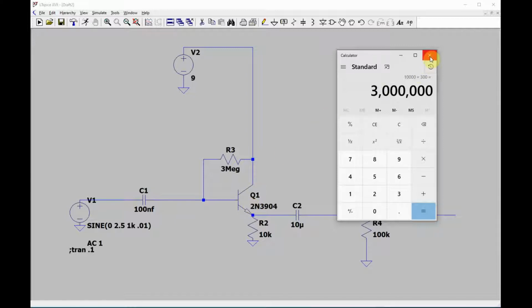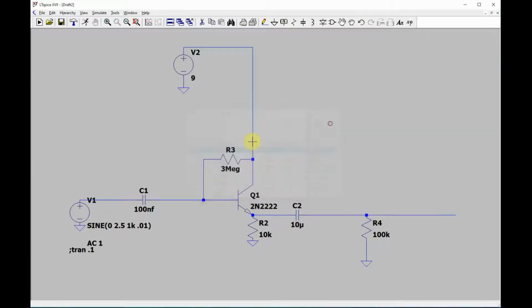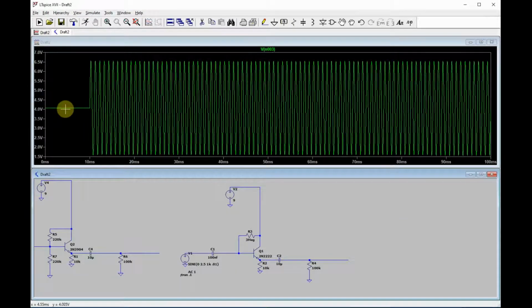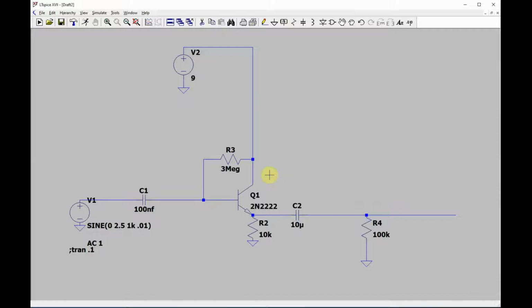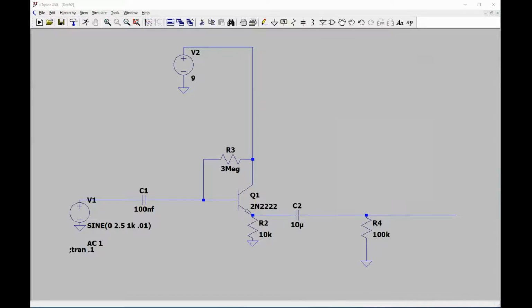Now, it's kind of hard to simulate, I think, but let's put a different transistor in. Let's pick this one. I bet that bias will drop a little bit. Yeah, it went down to 4 volts there. So this is below 300. Now, can't really simulate it, but let's just say you put a transistor in, and the HFE is 150 or something like that.